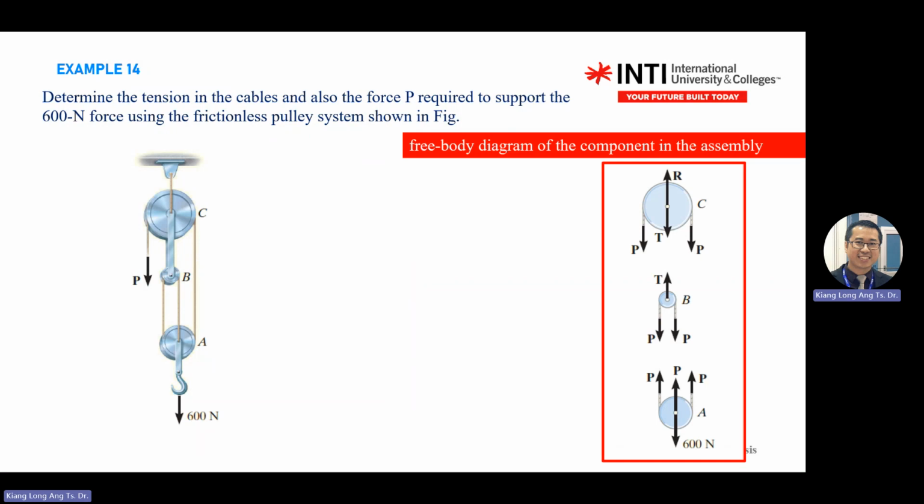Okay. So then there's a reaction here, going up. There's a cable. Although this looks like a pin, this pin is connected with one cable. So you don't have a C point CX, CY, but you have one cable going up here. So you write that as R or some force. Okay, so this is C. Any question for C? Makes sense? So then you move to B.